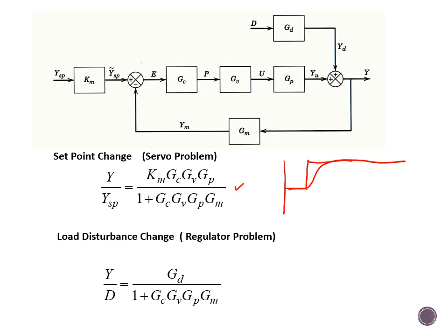And then the second type of feedback controller objective is the regulatory control loop. The regulatory control loop is one which responds to a change in some input variable, and then brings the system back to a steady state. So if there is a change in this variable, the process response will behave such that the system goes back to the steady state.